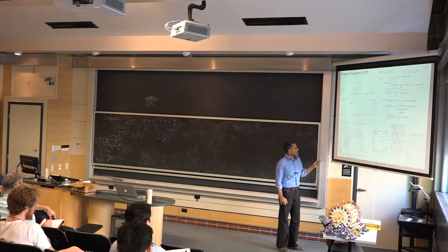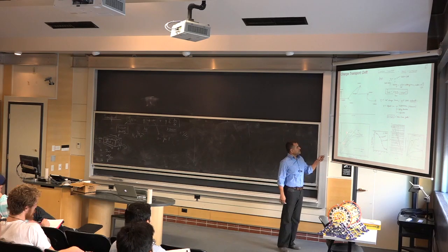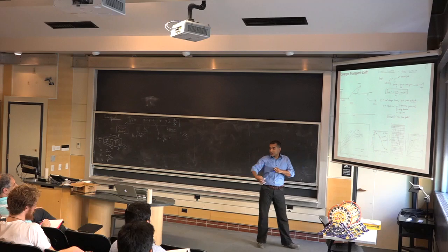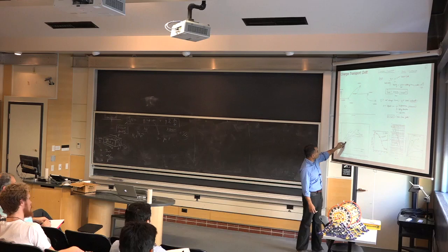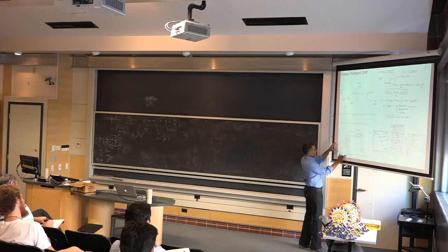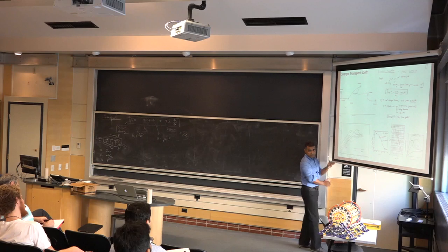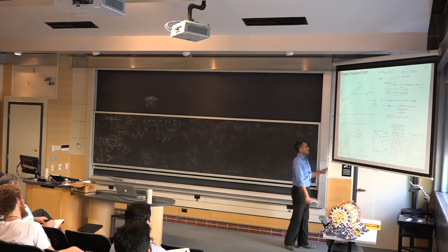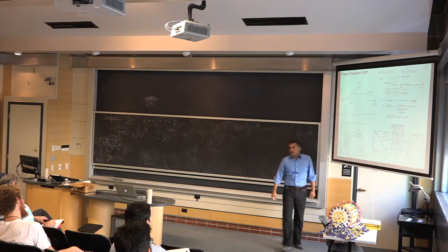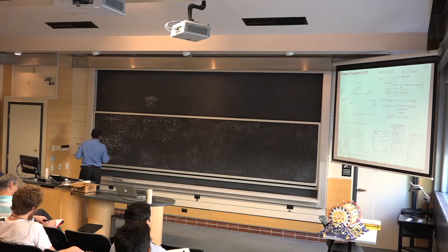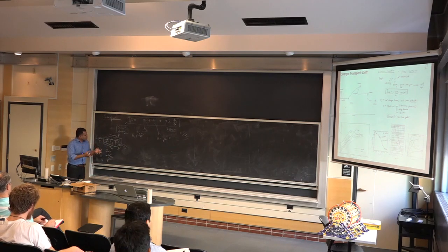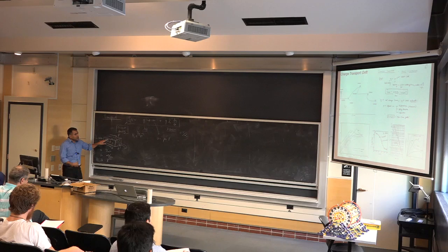In fact, there was a little question in the last class where I think Suren was asking what happens if you go into another valley. This is what happens when you go into another valley. You get negative differential resistance and that sort of thing. But right now, we're going to neglect that and say velocity initially increases linearly. When we say linear, if you have one order change in field, one order change in velocity, which is linear, a power law with power of 1. And then it saturates, and that saturation is because the electrons are now scattering what you call inelastically. It is losing its energy. So it's a non-ohmic behavior. So this is the saturation of velocity.